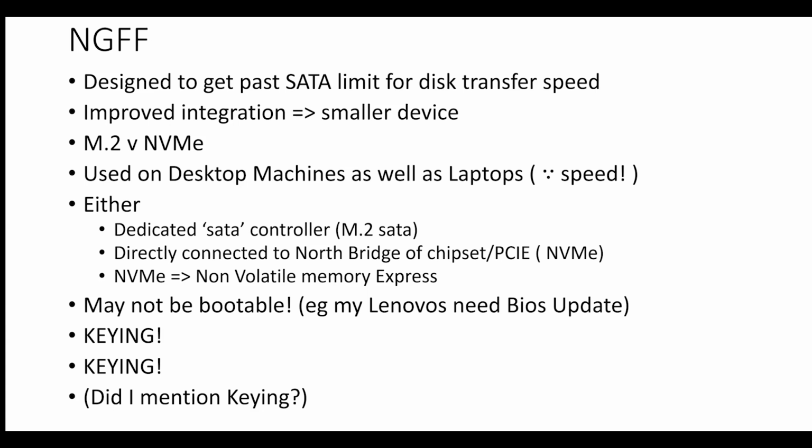So the drive that I just showed you is a SATA, it's a micro SATA. The NGFF doesn't use the SATA limit. It connects straight to the PCI bus. So it's back to how many lanes can you have? How much memory bandwidth can you have? And these things were so successful on laptops that they now use them on desktops as well.